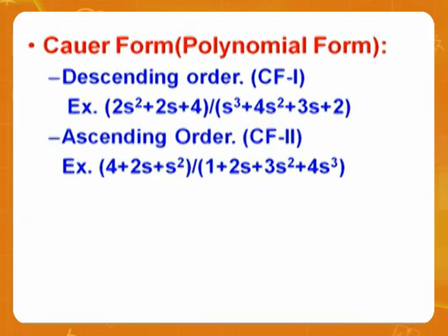If they are infinity, short circuit is happening in parallel, not accepted. Open circuit is happening in series, not accepted. That's why the residues should never become infinity. They can be 0. If any residue is 0, that particular component is missing, but that's not short circuiting or open circuiting. This is a very important precaution and statement about what K0 and K infinity mean.